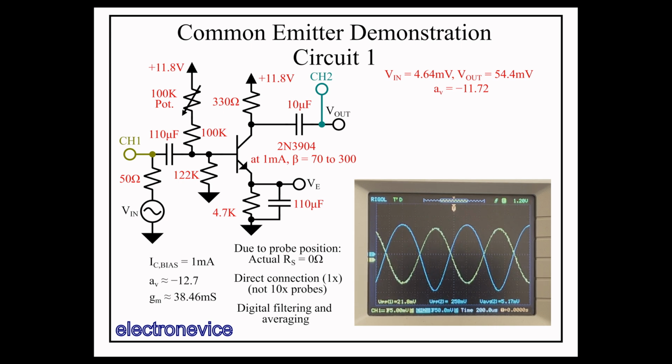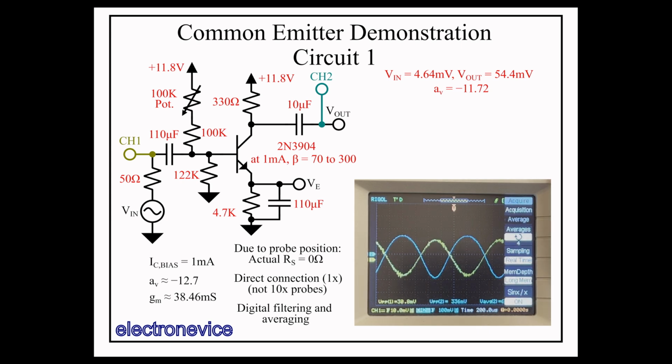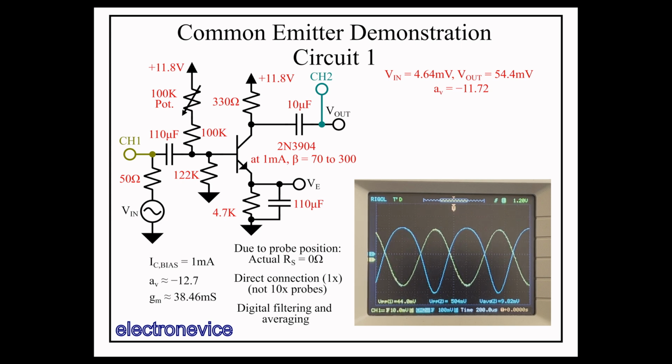Going to a higher voltage, with about 30 millivolts peak to peak, we can definitely see the asymmetry. This is a nonlinear effect which is caused by our small signal approximations breaking down. The small signal is not small enough. Continuing to increase the input voltage continues to make the nonlinearity worse, as we might expect.